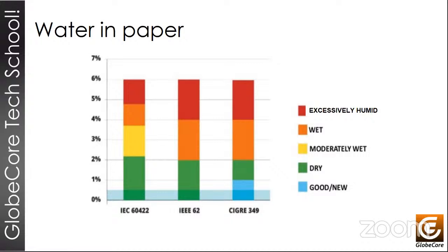High moisture levels in transformers are obviously undesirable, since paper is continuously being destroyed if there is water, and it's a very possible danger that a transformer may just stop, leading to a critical failure. And these failures are such that the transformer sometimes might not even be able to be repaired without serious effort. And in some cases, it just cannot be repaired entirely and must be written off.